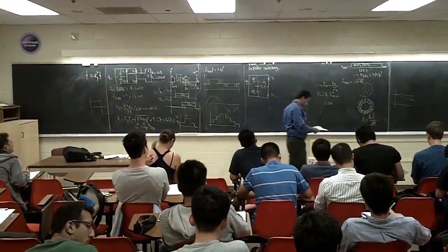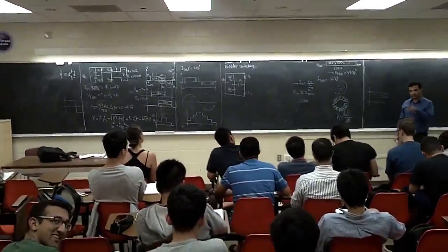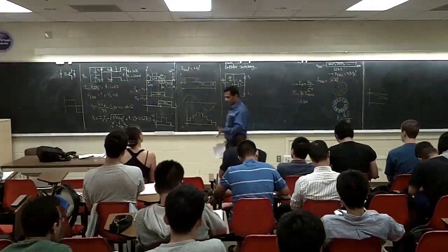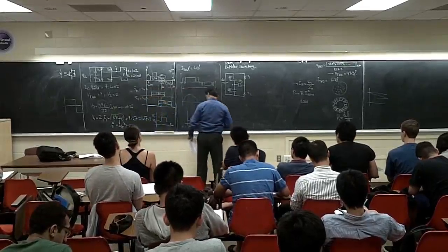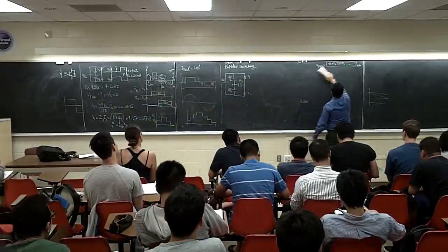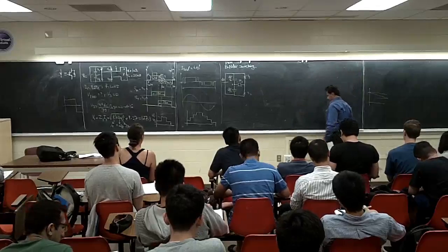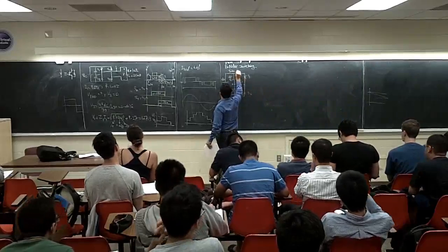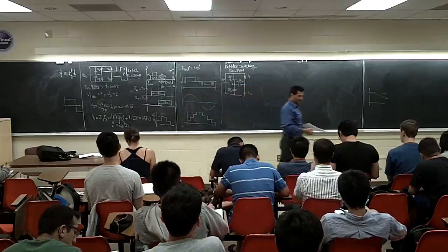Now, I told you to go with a harmonic elimination to calculate those alpha, beta, gamma, those things to get rid of the 3rd harmonic, 5th harmonic, 7th harmonics, or we can do this one. They call it sine PWM. Or they call it sine delta PWM.